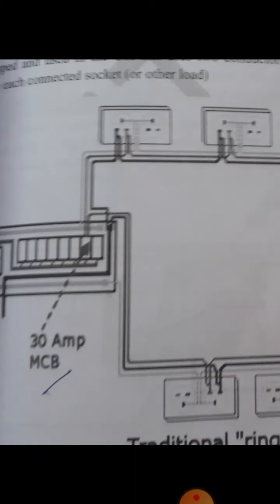If somebody is using some equipment from the power socket and there is some fault, this breaker is going to trip. And for the lighting wiring system, we especially use only MCB. In the bathroom, for the bathroom light, we also use ELCB, because inside the bathroom there is water. For bathroom and toilet wiring and circuits we use ELCB or RCCB. But in normal areas, like the bedroom and other normal areas where there is no risk of water, we use MCB.